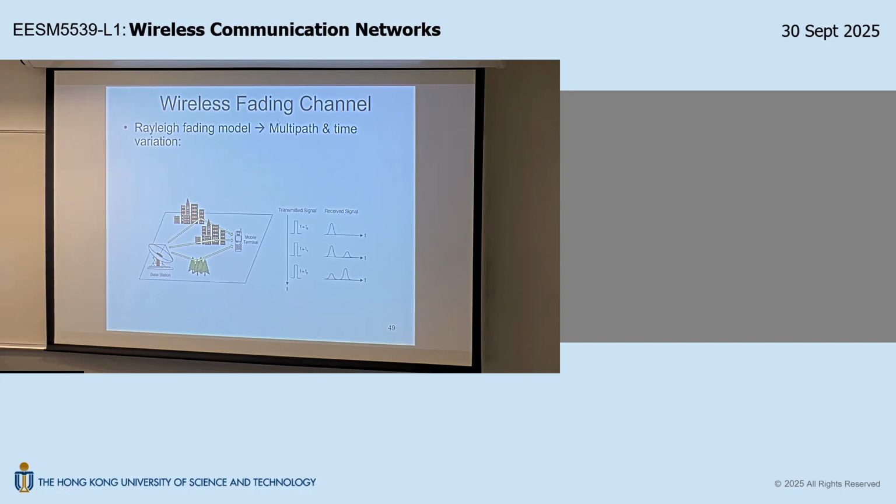Now, let's say the transmitter is only radiating energy within a certain angle, theta. Okay? So, in this case, after some distance, d, we have a certain solid angle area. Now, we can, of course, use multidimensional calculus to work out the area in terms of the distance, d. But we don't even need to do that. One thing we can be sure of is this surface area scales like d squared. For sure, this is fundamental geometry.